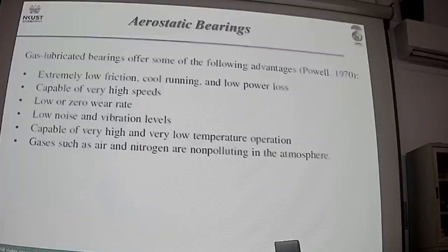So if you run an oil hydrostatic spindle at a very high speed, it generates tremendous heat, which has to be cooled down. So it's not really practical to use the hydrostatic bearing at very high speed.